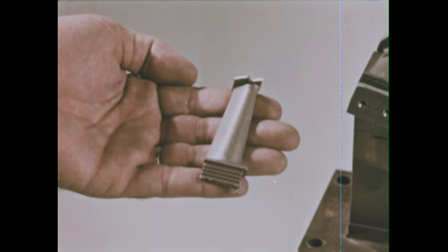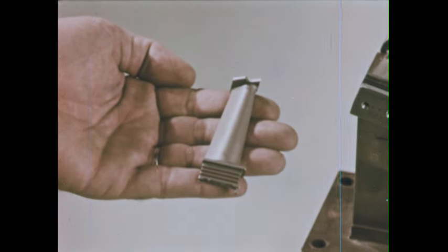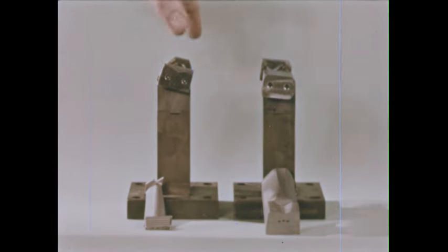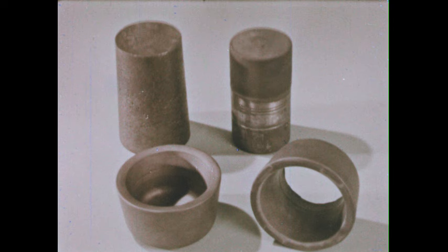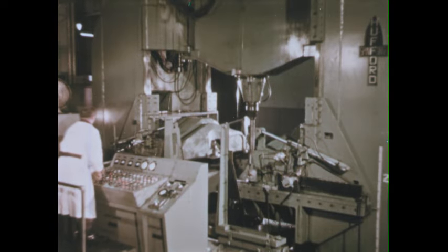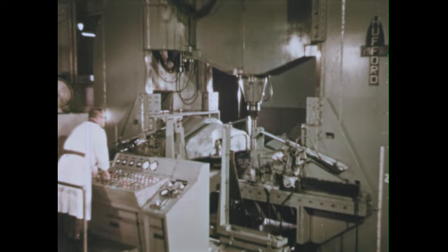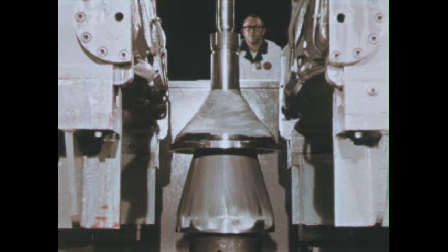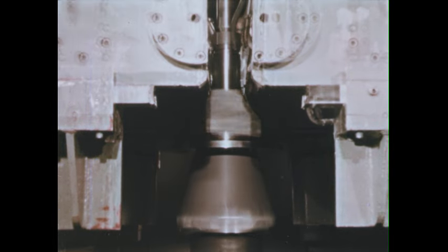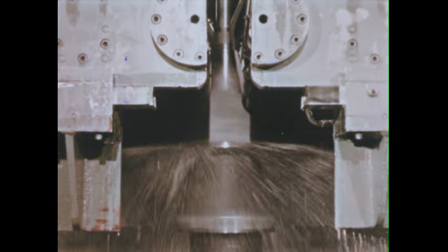Just the opposite of electroplating, huh? Correct. This finished turbine bucket was shaped from high-temperature material. And here are the shaped electrodes that were used to do it. The process replaces a dozen conventional machines and produces a yearly savings of about 80%. When subjected to enough pressure, metals become plastic and are easily formed. This vertical shear forger produces turbine compressor shafts at a savings of $1,500 per part.